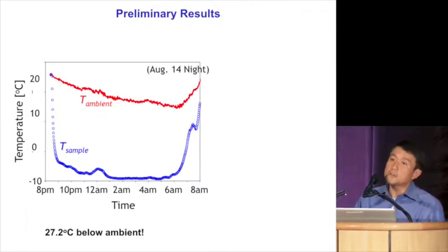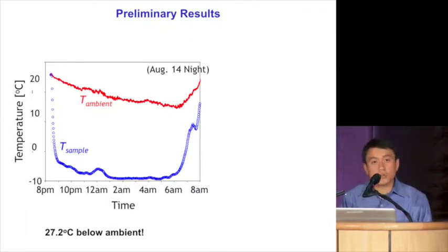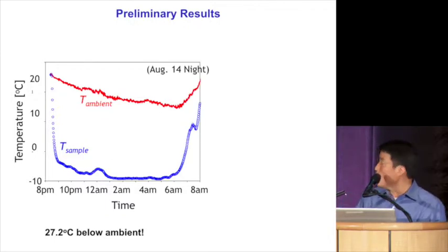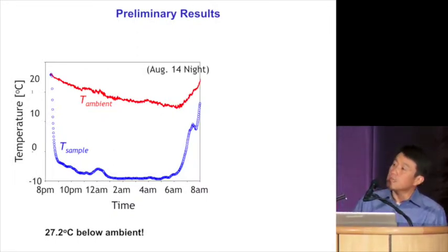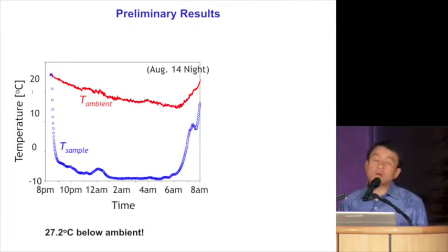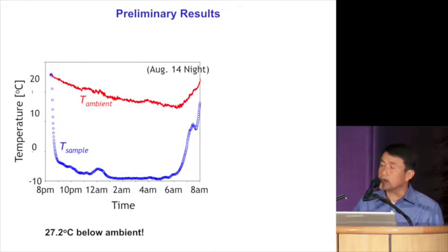This is a vacuum chamber. We use vacuum to cut down the convective loss. We use a radiation heat shield to cut down the parasitic back radiation from the surroundings. And we also design all the conductive pathways carefully in order to cut down the conductive heat leakage.